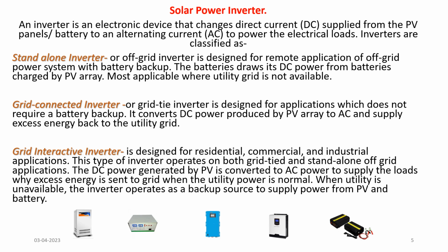Then another thing is that we have some types of inverter that are pure sine wave. You can see some they call modified sine wave. You can see square wave, but mostly what is good for appliances is the pure sine wave inverter, because square wave is not good for our electrical appliances, apart from maybe an industrial setup, like electric motors and stuff like that.